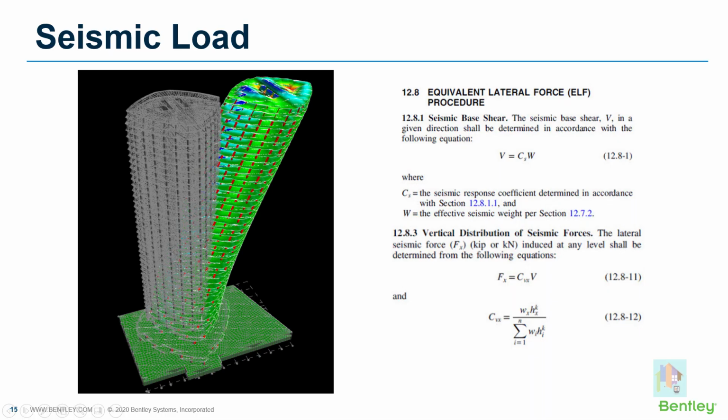Now coming to the seismic load application. Tall structures are more vulnerable to earthquake. Seismic force, base shear and story shear values are proportional to the mass of the structure, and for any tall building, overall gravity load or seismic weight is considerably very high, which increases the seismic vulnerability. It is always a challenge to minimize the seismic effect.